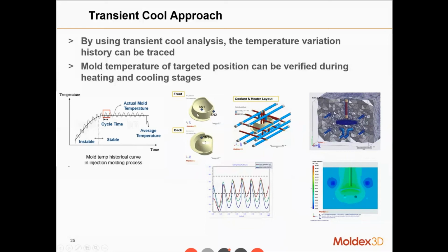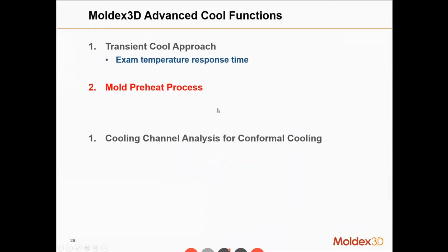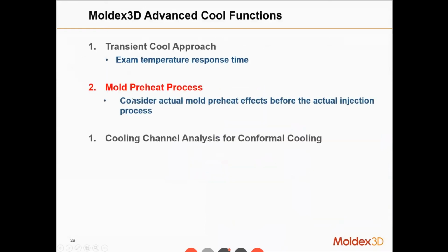One thing that you can do is set sensors inside a mold or on the part to detect the temperature progression throughout different cycles, to let you know if there are some kind of huge fluctuations that could affect the quality of the end product or the filling behavior throughout each cycle.